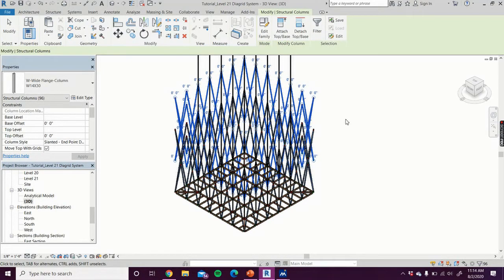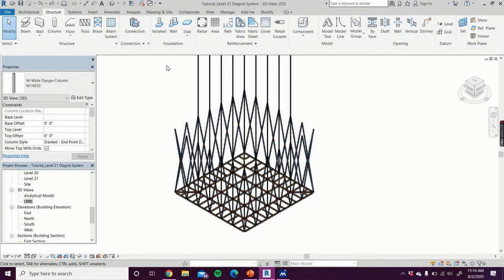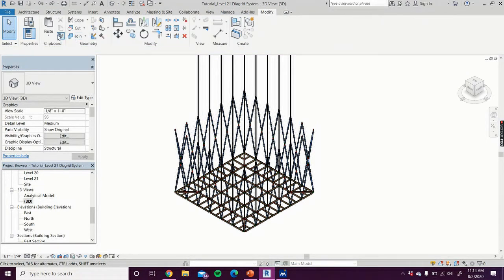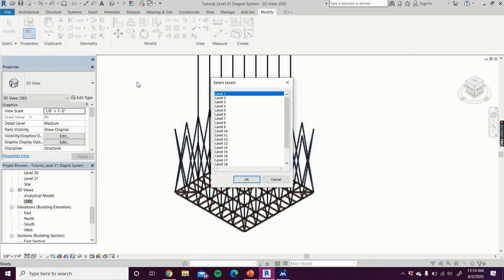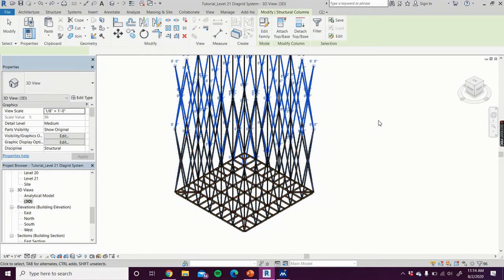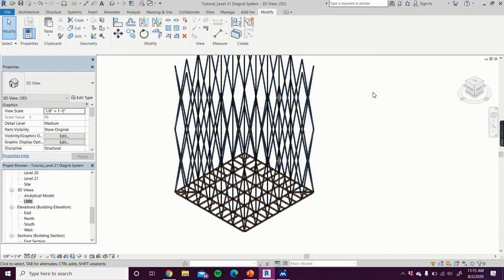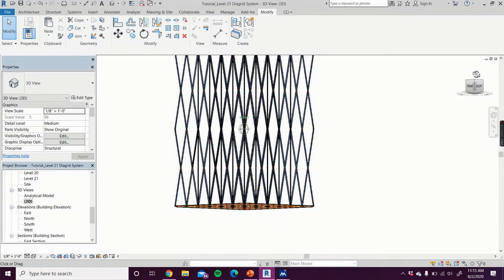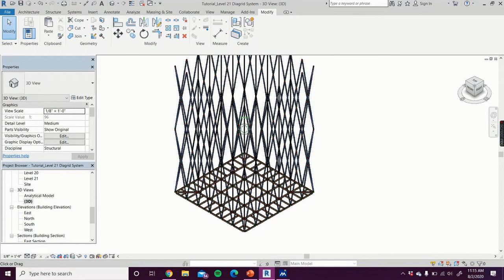Something about that doesn't look right, so I'm going to Control Z that. Still copy to the clipboard, so paste aligned to selected views. If that happened, somehow it accidentally aligned to the wrong floor, maybe level 5 instead of level 9. So I'm going to go to level 13. Okay, there we go. Like I said, it's always good to check in 3D view. Yeah, it looks pretty good to me.